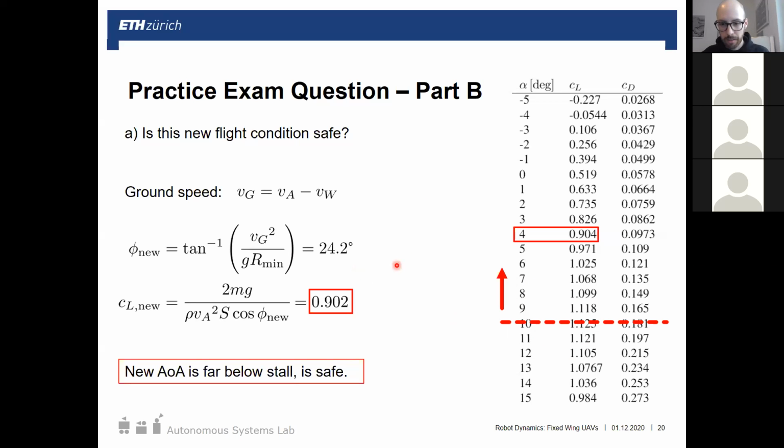Okay, another question here. What if the angle of attack is larger than 10? Since 10 is our stall point for the tech pod, then we're still stalled. We're just getting more and more separation of the flow over the surface of the wing, as I talked about with that continuum earlier. We're getting worse and worse, so the lift drop-off is just going to keep going down in this case.